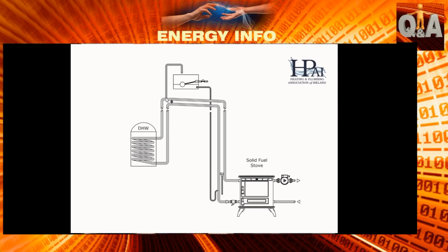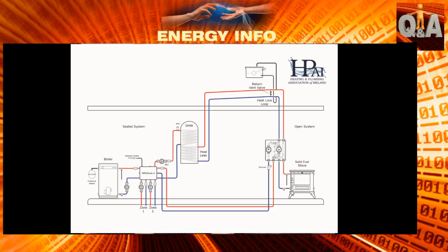Here's again a situation. I know there are other devices on this, and we're not particularly talking about them today. So all I'm really concentrating on is the flow and return off the stove, how they rise up through an energy link in that situation, but forgetting that, comes to a high point first and then falls across the attic. To my mind, that's the very best system, because you have your high point catching any air, and also when it comes back down and the water has lost its heat and rises back up, it rises again to the high point where the half-inch vent is, and that vents all the air out and back down again to the stove. So you've got your neutral point, or the top of the barrel, is created by the top of the tank, of the expansion tank in the attic.